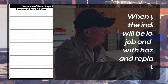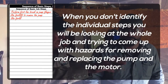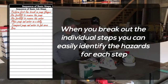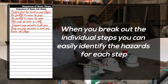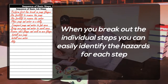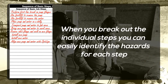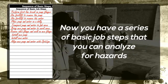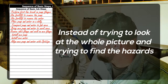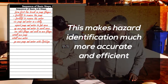Without identifying the steps, you will be looking at the whole job and trying to come up with hazards for removing and replacing the pump and the motor. With the steps broken out like we see here, you are now coming up with hazards for performing the lockout tagout, performing the first line break, using a forklift, transporting the pump and motor, and using hand tools. You have 8 sequential steps that you can analyze for hazards instead of looking at the big picture and trying to figure out the hazards. This makes hazard identification much more accurate and efficient.